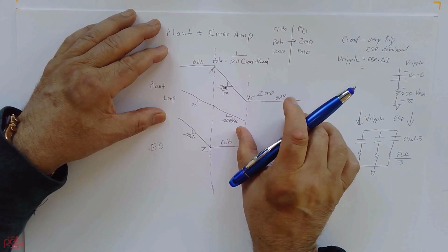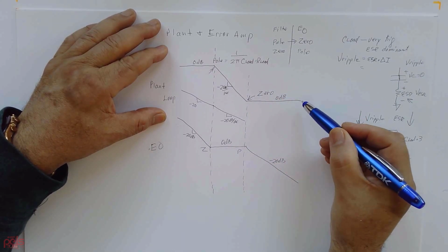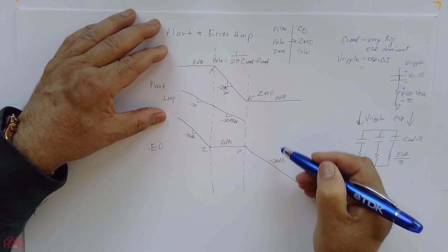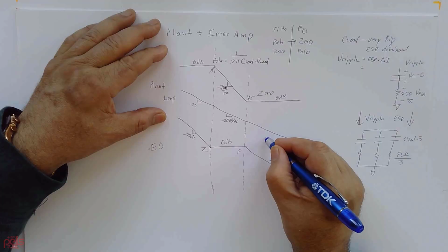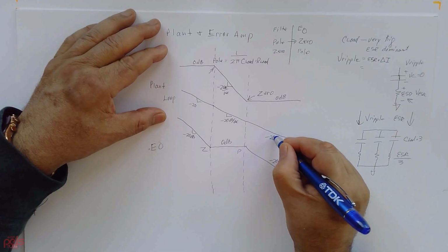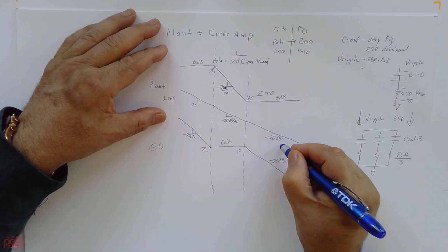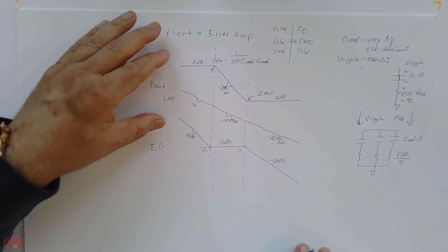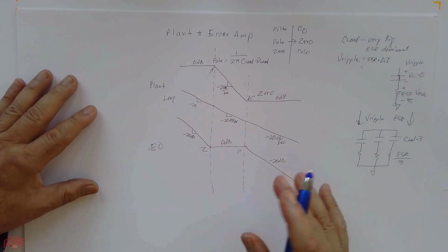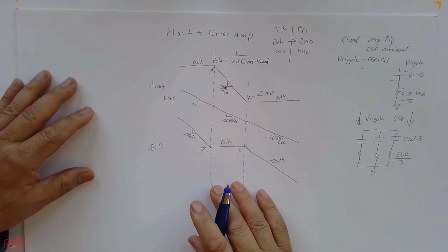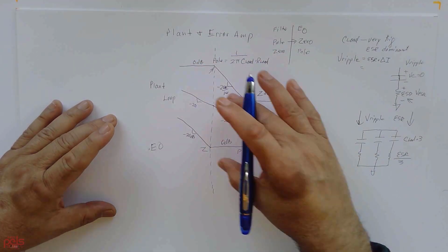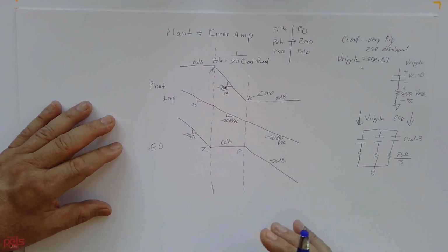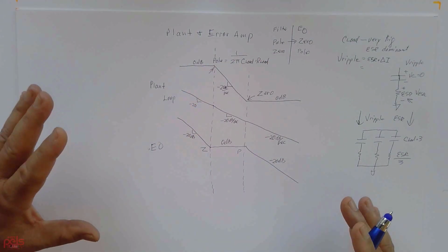In the last interval, 0 dB plus negative 20 dB, you end up with negative 20 dB per decade. That's the powerful technique that Jack taught me: if you can cancel these, it makes compensation very, very easy.